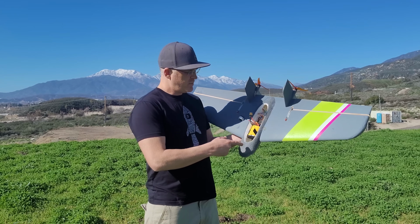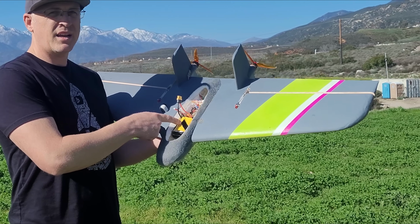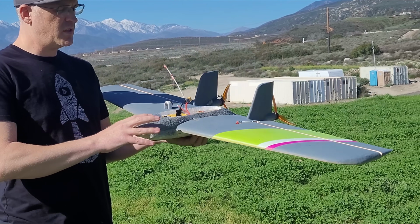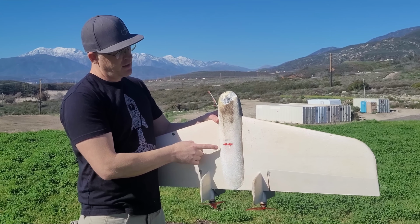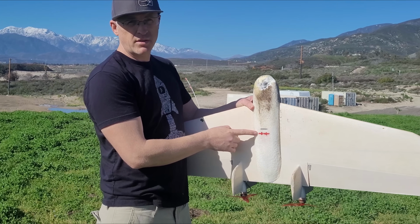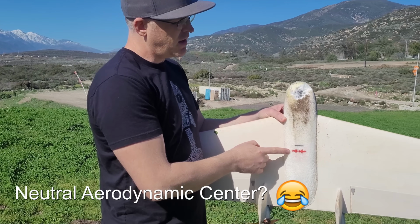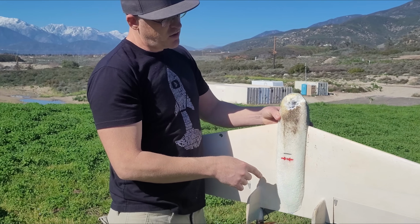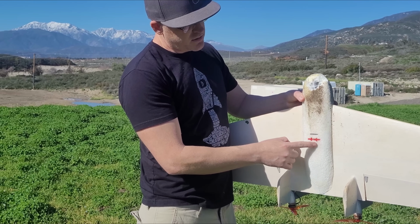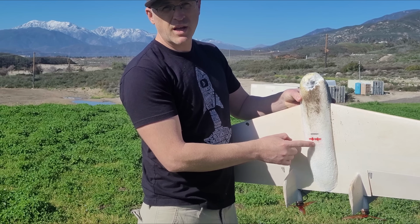Okay, so I moved the battery from the nose and I had to move it back to where the unstable position is. Before I moved the battery, the plane balanced here on the black line, and the neutral point was the neutral aerodynamic center of the aircraft. So now that I've moved the battery back and I've taken out some nose weight, the weight is back here behind the neutral point, okay?